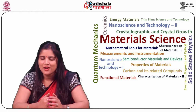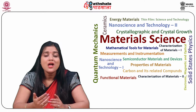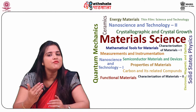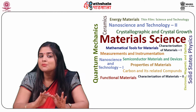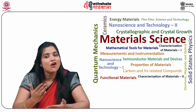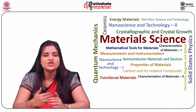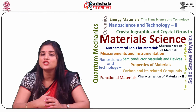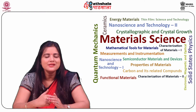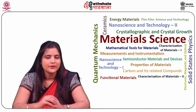An operational amplifier, which can be abbreviated as op-amp, is a direct coupled high-gain differential amplifier that uses voltage shunt feedback to provide a stabilized voltage gain. It is called operational as it was used originally to perform the basic mathematical operations such as addition, subtraction, integration, differentiation, etc. And the word amplifier specifies its capability of providing the voltage gain.